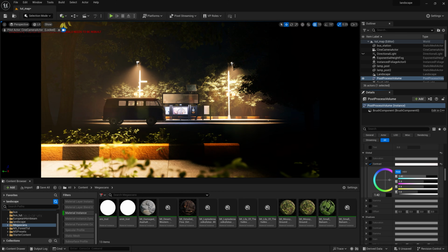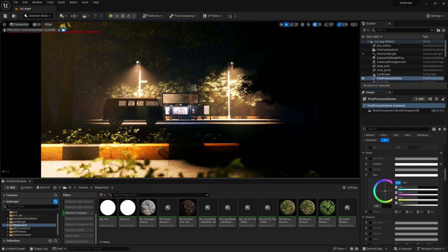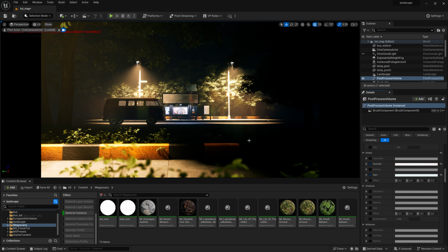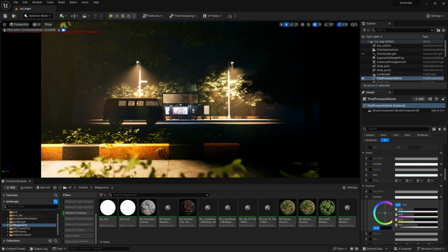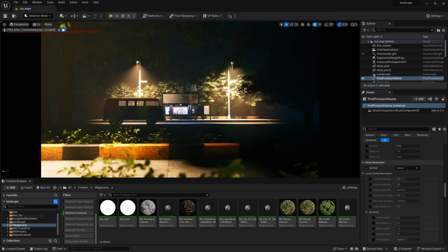Yes, it's actually required. So just increase the CC right from here. And now let's add some gain. So the gain can control the highlight areas. Okay, so if you decrease, you can see the highlights are going a little down. So what I'll do, I'll just increase the yellow intensity, and after that you can find the shadow. So this works only on the shadow area. Currently the shadows are pretty dark, so just decrease it so that you can see some depth. And now let's do some camera animations and the final render.